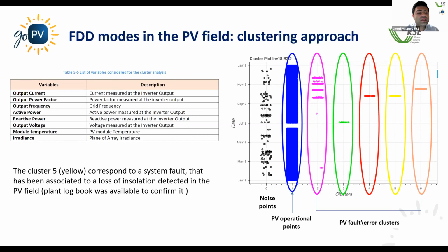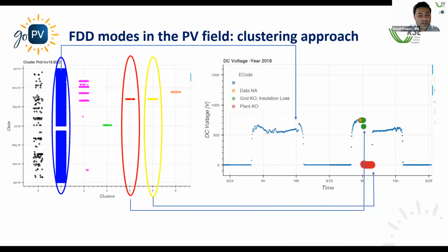The advantage is that it can detect faults and continuously learn about new possible faults that previously were not labeled, for example, due to new components, new failure modes, or new PV technologies. So once discovered, like in this case, each cluster is characterized. The new pattern of fault can then be classified, so it is classified and labeled by the system for later recognition.